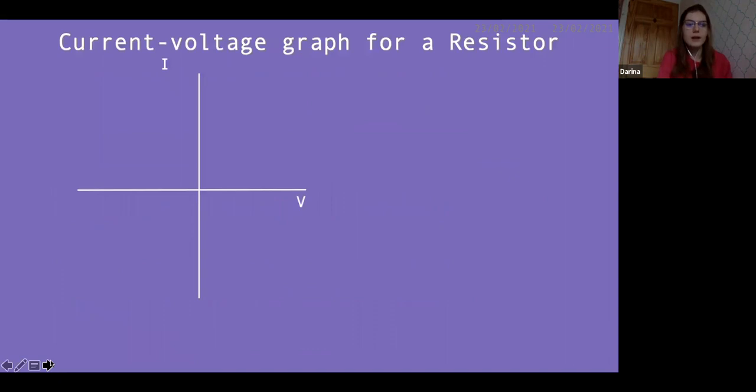The next thing that I wanted to mention is what Ohm's law actually means. If we rearrange the equation, we can map it to a graph. Usually we have V equals IR, but graphs are drawn with current on the y-axis and voltage on the x-axis. So to rearrange it in the form y equals mx plus c, we would have I equals 1 over R times V. So that's our y, that's our m. Remember, m is gradient, and that is our x.